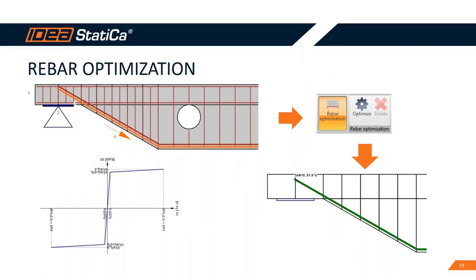As a second big development was rebar optimization. So we will show the real practical demo, and the rebar optimization is a tool which is finding out the minimal amount of the reinforcement in a detail and trying to optimize and design the reinforcement which will be fully utilized.